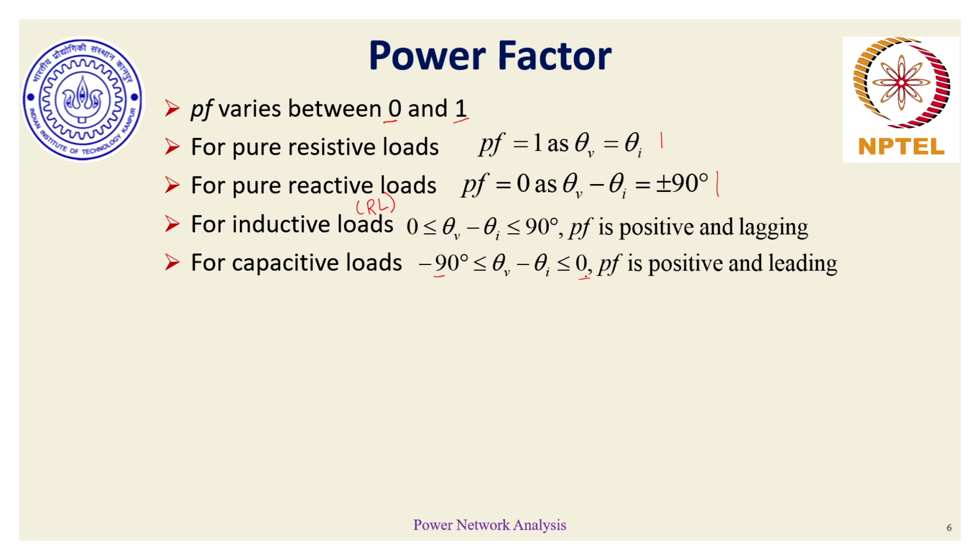Coincidentally, cosine of the phase angle is independent of the sign of the phase angle. So, to segregate the power factor value, the notion of lagging or leading comes in. For inductive loads or capacitive loads, which can be replicated by a combination of R and C loads, power factor will always be a positive number.